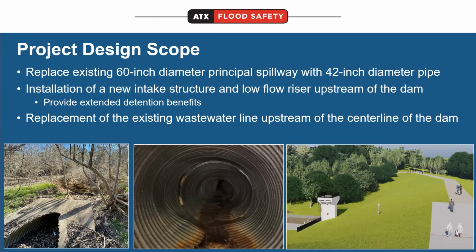You can see that there's sections that are broken or corroded and misaligned. So obviously not in good condition. In the left picture here, that's the inlet to that pipe on the pond side, on the reservoir side. It's at the level of the reservoir, but some of the material on top of the dam of the pipe has been eroded.